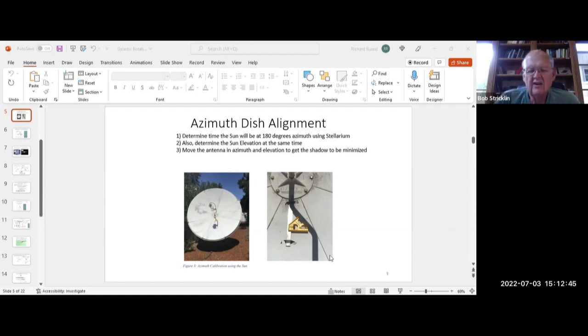I agree. On your timing thing, I was going to make a comment about that too, from an engineering point of view. Whenever we measured the speed of something or the rise, you usually would measure the rise time of a signal from the 10% to the 90% point. We set it up on an oscilloscope, and the oscilloscope has dotted lines that have been put there in the past for that purpose, to help you find the rise time of something.